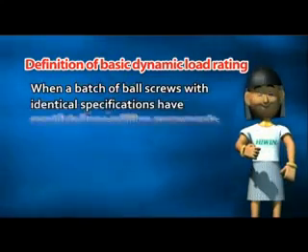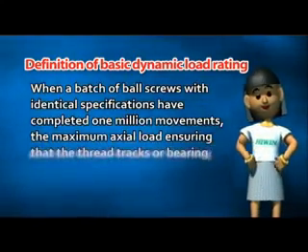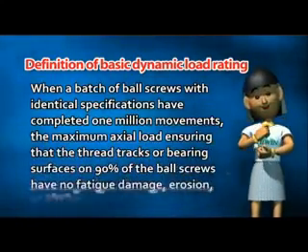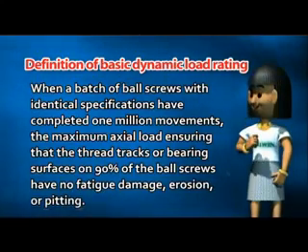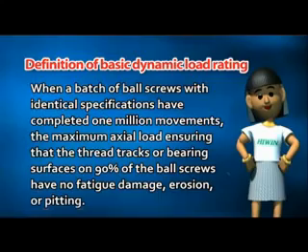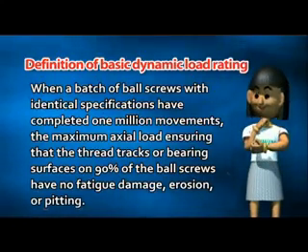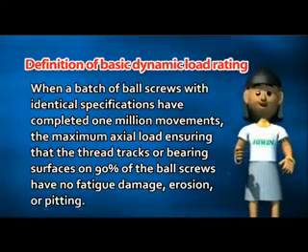The basic dynamic load rating is therefore defined as follows. After a batch of ball screws with identical specifications have completed 1 million movements, the maximum axial load ensuring that the thread tracks or bearing surfaces on 90% of the ball screws have no fatigue, damage, erosion, or pitting.